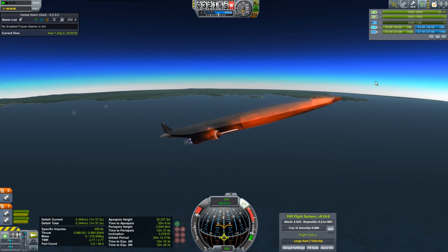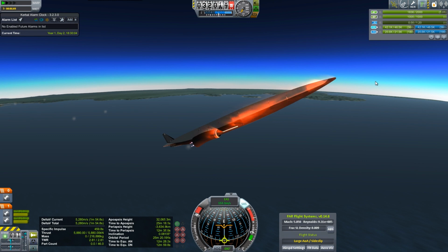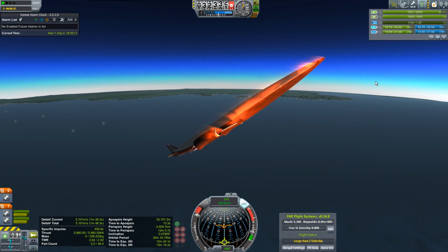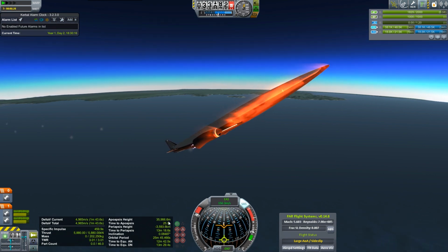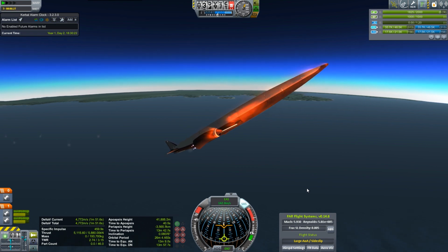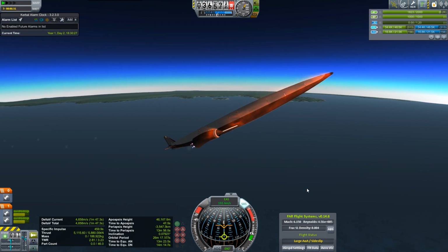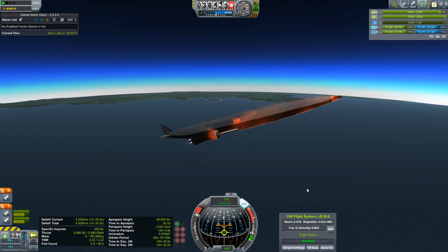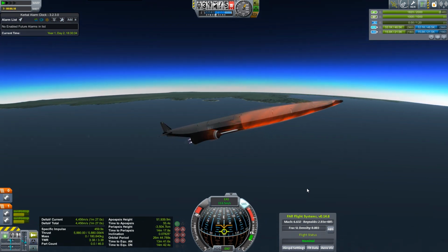Okay, gone to closed cycle mode, significantly more thrust. I'll do a big pitch up maneuver to try and gain a lot of altitude very fast. I want to see that direction marker get, say, 10 degrees above the horizon, and we'll see that our timed apoapsis is also climbing a great deal. Pulling more than 3 Gs. Throttle back some. Yeah, right about there. Okay, and then I'll start pitching forward to do a more efficient burn. Actually, throttle up again, and kill that trim.